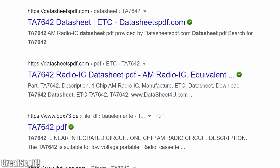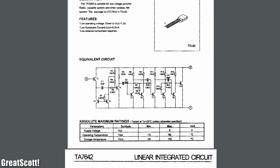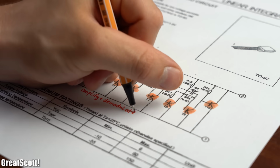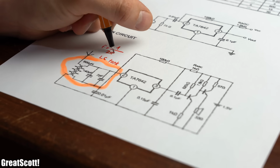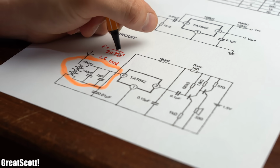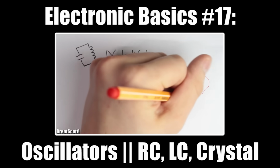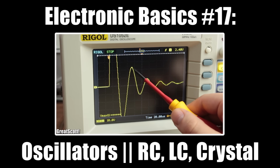But finding a proper datasheet for this old IC was not easy, but eventually I found this. It seems like the IC consists of a couple of transistors, which not only amplify our received AM signal, but also demodulate it. That means that according to the application circuits, we simply have to build up an LC resonant tank circuit, whose resonance frequency is close to our AM signal. And then the IC should simply spit out the amplified signal on the outputs. And if you're now wondering what an LC resonant tank circuit is, then make sure to watch my video about oscillators.